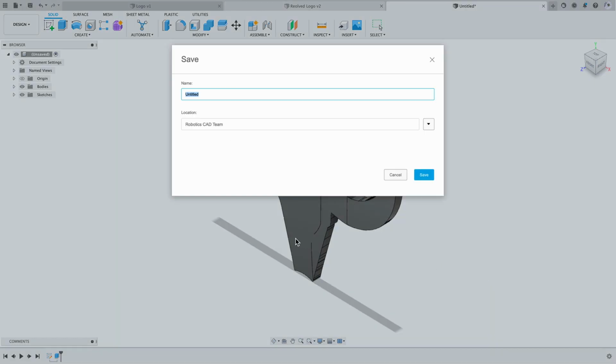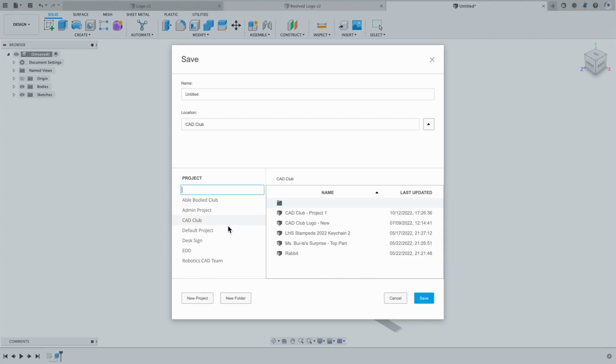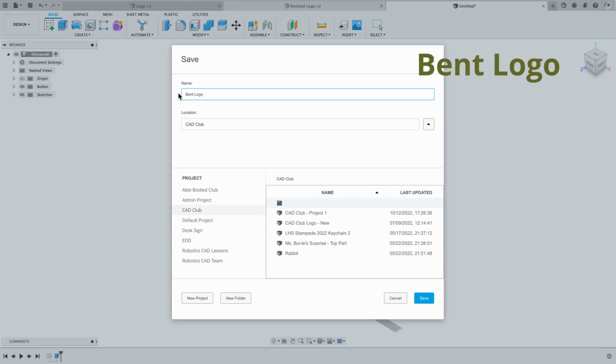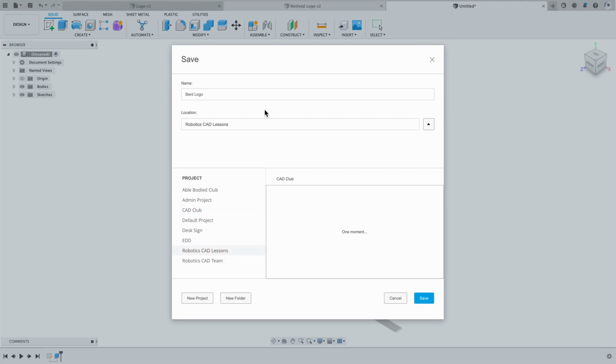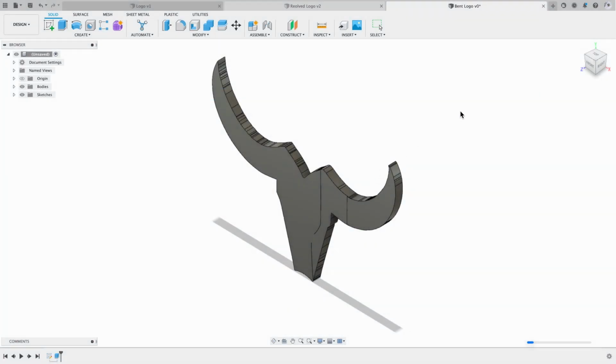Right now, let's go ahead and save the team game element, create a new project in Fusion 360, and a new folder inside that project. The project, you can call it Robotics CAD, and the folder you can call team game element, and we have to save our team game element in there. After you saved it, go to the file, export into an Inventor IPT file.